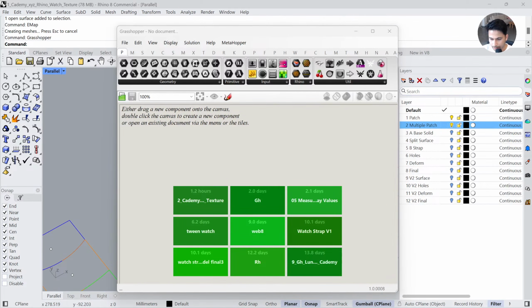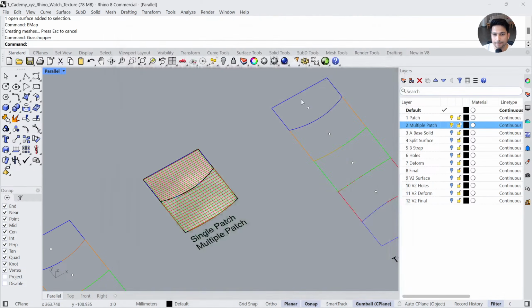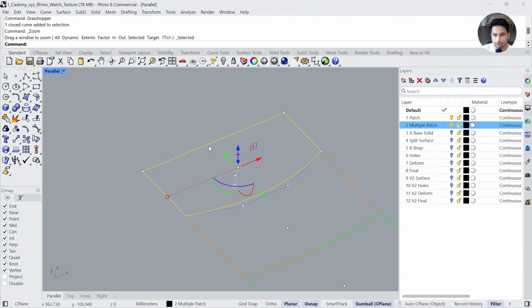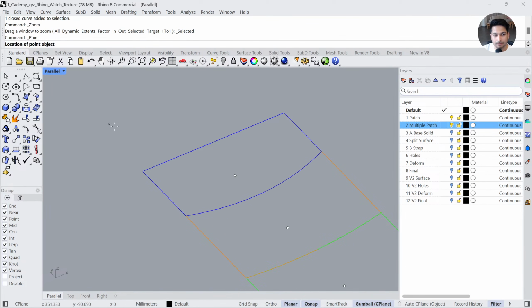Okay, what does the sample point factor affect during the patch command? You just leave it to 1. Yeah, the default setting is 1. It's basically, if you use a lower number, it will be recreating many points on the curve so that it can use that as a reference to build the patch. So the lower number will give you a more accurate patch, okay?